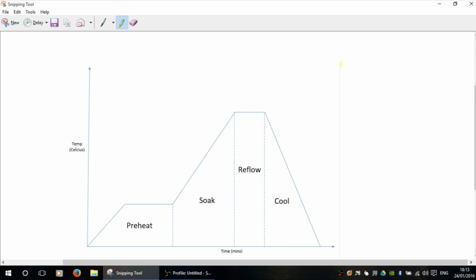The machine that was built before yours may very well have used the last plate in that last batch. Yours may be different. Again, this is why BGA profiles need to be built specifically on your machine by you. And just going back to that humidity point on the expansion of moisture.